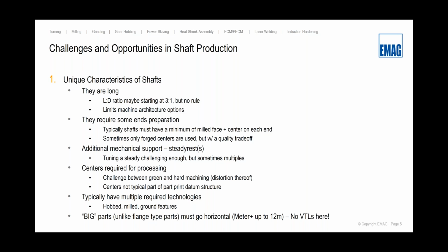So you do have to be very aware of what the tolerance stack up is to your centers, because ultimately those centers, once that component is assembled in whatever it is, a gearbox, this, that, or the other, the quality of those centers as it relates to a journal bearing or some other feature, really it goes away. So you do have to take care of your datum structure and your tolerance stack up to your centers.